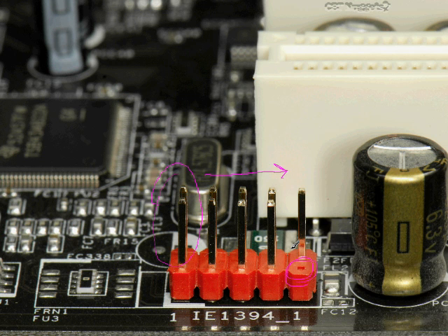Well, that causes a problem because some of these pins are for transmitting and receiving data, and some of them are for power and ground. And if you shift this over to the right accidentally and leave part of the block dangling off the side and leave these exposed, then you're going to be shooting power into a location on that block that was never designed for power. So you could totally short out or ruin your entire 1394 capability on the motherboard.